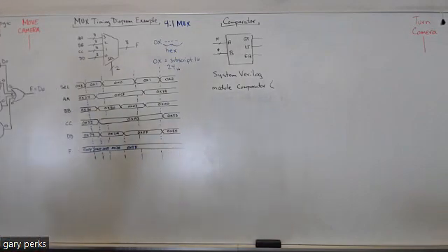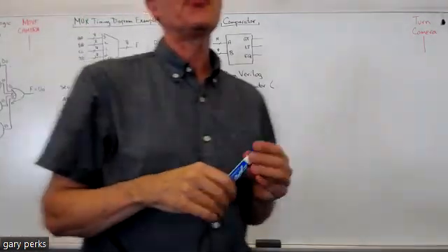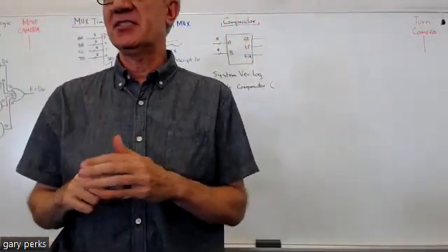But starting today, and for the rest of the quarter, and when you take the next class, CP 233, we're going to start showing you code where you let Vivado do the work. Instead of you coming up with the Boolean expressions from a truth table, we're going to start using if statements and case statements to model our hardware. And for the MUX that you'll be designing for Lab 3, we want you to use an if statement.